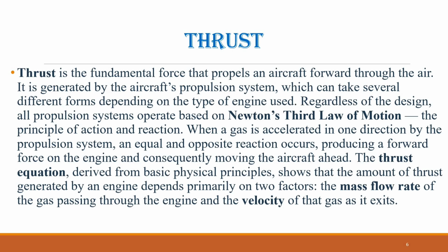Regardless of the design, all propulsion systems operate based on Newton's third law of motion, the principle of action and reaction. When a gas is accelerated in one direction by the propulsion system, an equal and opposite reaction occurs, producing a forward force on the engine and consequently moving the aircraft ahead.